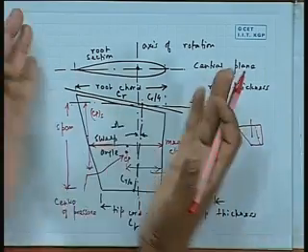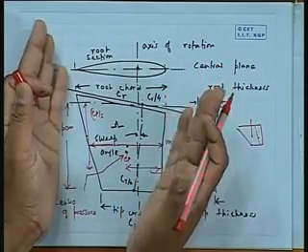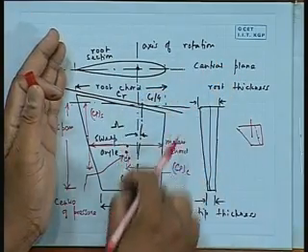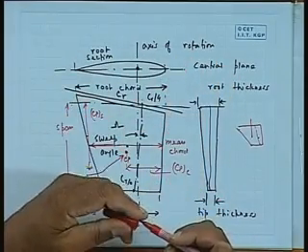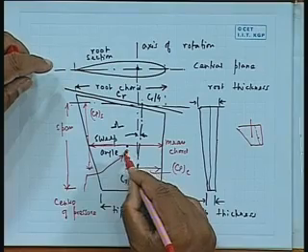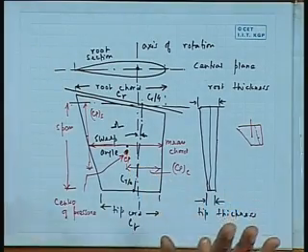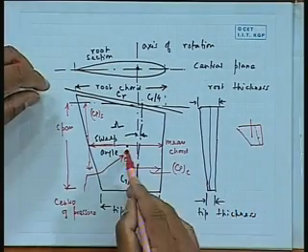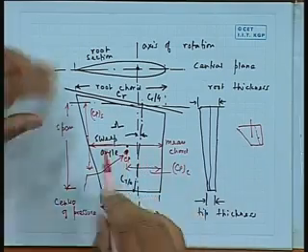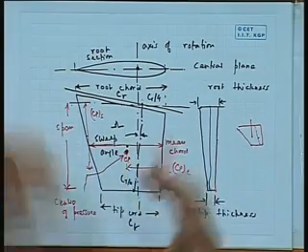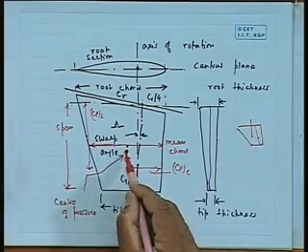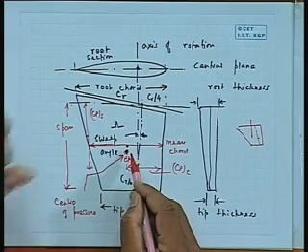There are two lines there, so the standard has become that you take 1/4 of that from each and take that line and find out how much that line is inclined with respect to vertical. That is all. Then you have a point where the entire force will act. You can call it center of pressure or center of force, and now you measure the center of pressure's chord length, and define where it is located.